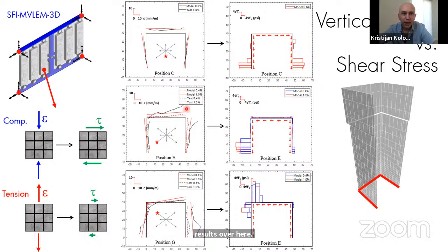What this is really comparing, on the right side, we have the shear stresses that result at the base of the wall. On the left side, we have the same strain distributions. And what these results are showing is that the shear stress is only resisted at the fibers where you have axial compression, right? If the fiber is in tension, that fiber is not going to resist any shear stresses. And this is actually something that's realistic, right?